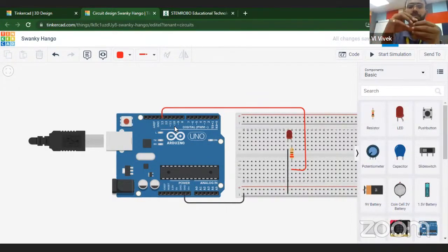In case of that type of projects, like you will make a robot, now you can control the speed of the motor. कि अगर आपको speed को control करना है motor की, robots की, then you will use number 3, number 5, number 6, number 9, number 10, number 11 pins. Like जैसे अगर मैं बात करूँ in case of LEDs, I have connected directly to pin number 13. Okay, because I know very well कि each pin is a digital pin, तो इसलिए मैंने इसको 13 नंबर पिन पे कनेक्ट कर दिया.